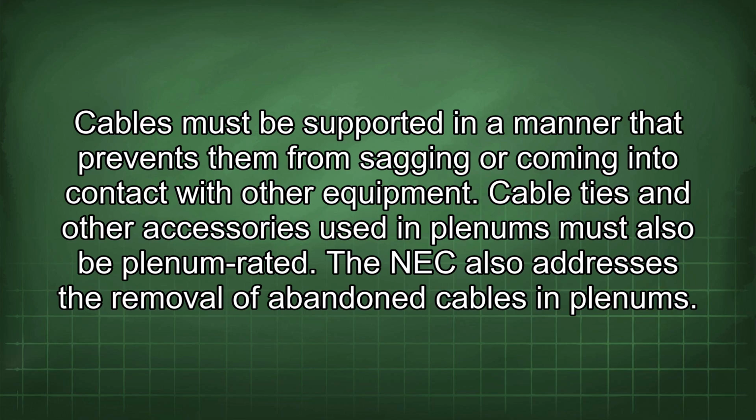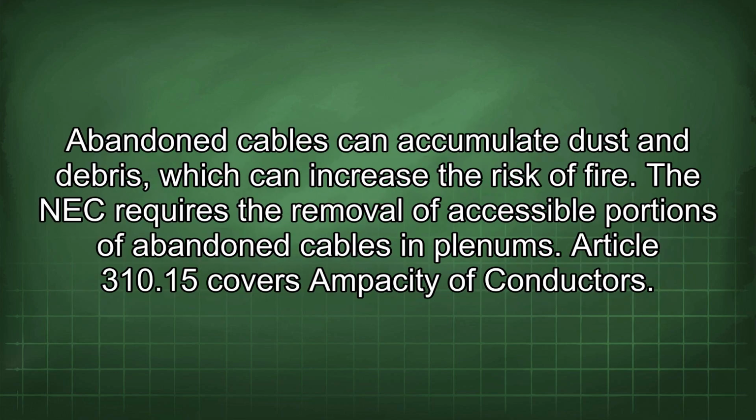Cable ties and other accessories used in plenums must also be plenum rated. The NEC also addresses the removal of abandoned cables in plenums. Abandoned cables can accumulate dust and debris, which can increase the risk of fire. The NEC requires the removal of accessible portions of abandoned cables in plenums.